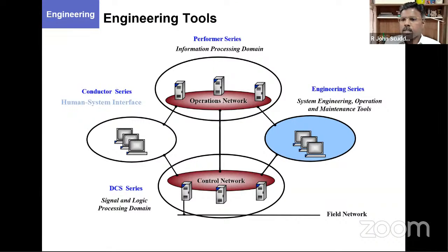So it opens and you can put all the function blocks that are needed, and you can assign input modules and output modules for that. Once a logic is formed, you need some inputs, and based on those inputs, you will be giving out some outputs. All these can be put in some sheet, something similar to an Excel sheet, 1, 2, 3, and you can be making a lot of logics.